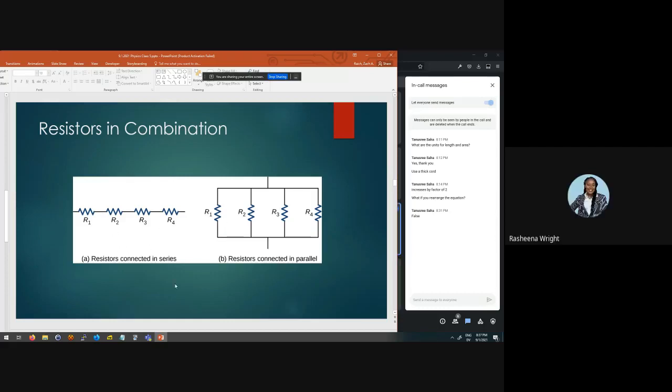It's the same rule. You can talk about any component being in series and parallel. You can actually have batteries in series, and you just add up the voltages. And if we were covering inductors, you can have inductors in series and parallel. Same definitions of series and parallel. It's just the equations are opposite for resistor versus capacitor.